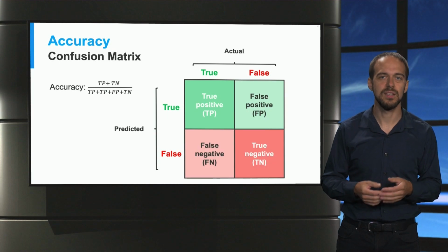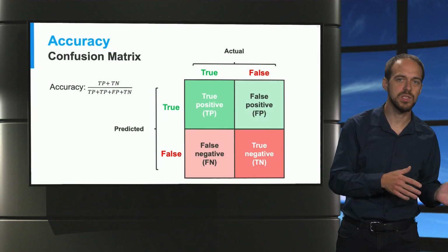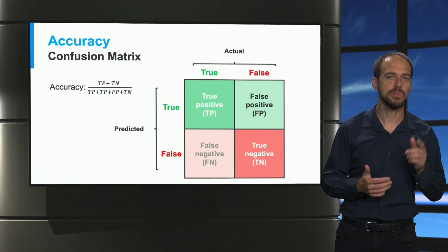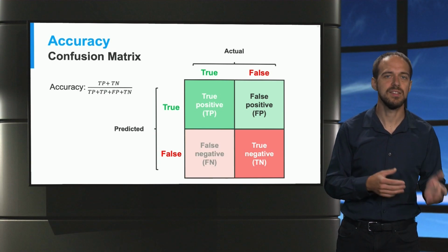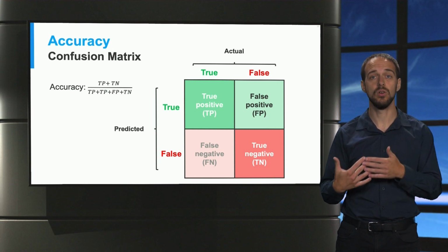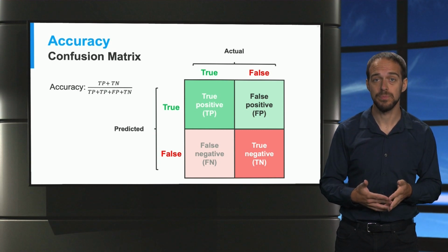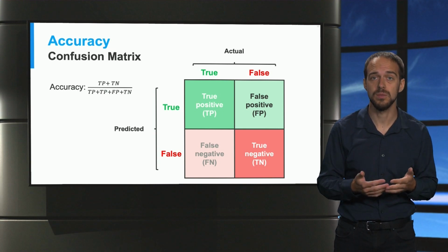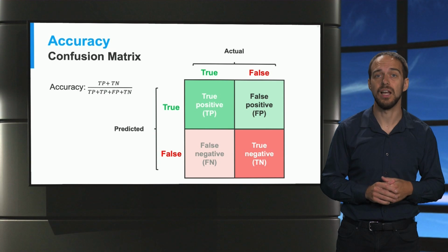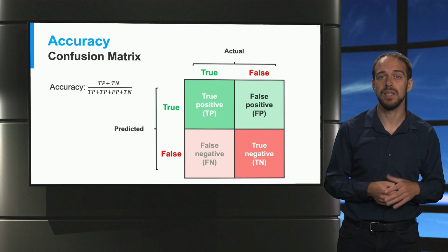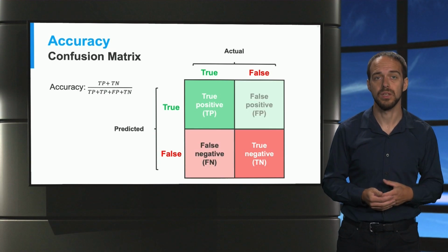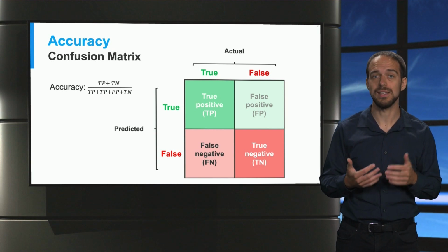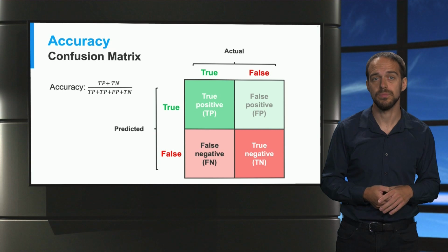But then there are two inaccurate classes, false positives and false negatives. One of them is worse than the other. A false positive means that an insecure operating condition was predicted as secure. This can be severe because if we are predicting a safety critical metric of a power system, we must not miss an alarm. If we miss the alarm, then a power blackout may occur. A false negative means there was a false alarm, which is not as catastrophic as a false positive.